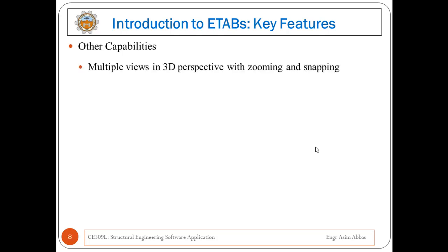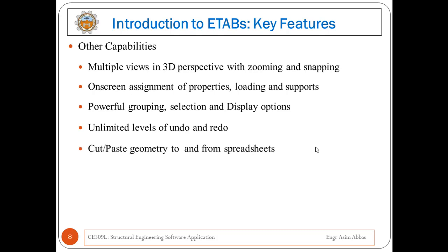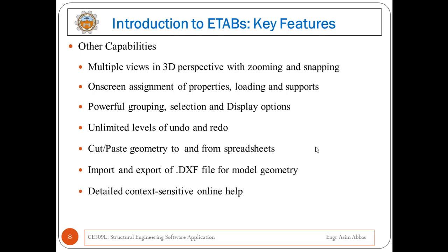Okay, other capabilities include multiple views in 3D perspective with zooming and snapping option, on-screen assignment of properties, loading and support, powerful grouping, selection and display options, unlimited levels of undo and redo, cut and paste geometry to and from spreadsheet, import and export of .dxf file for model geometry to and from AutoCAD, detailed context sensitive online help, and the analysis is integrated with post processing and design capabilities.